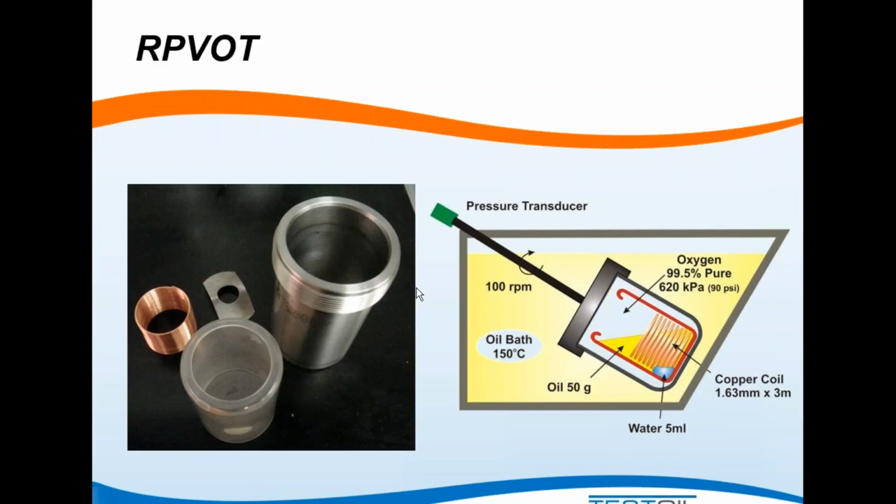So we know that, when oils oxidize, they're going to take that gaseous oxygen that's in that pressurized vessel, and they're going to convert that into like a solid. It's going to turn into acid is what it's going to do. So once that starts to happen, once we overcome the antioxidants and we start uptaking oxygen, the pressure is going to drop. And the end of the test is defined as a drop of 25 psi from its maximum.